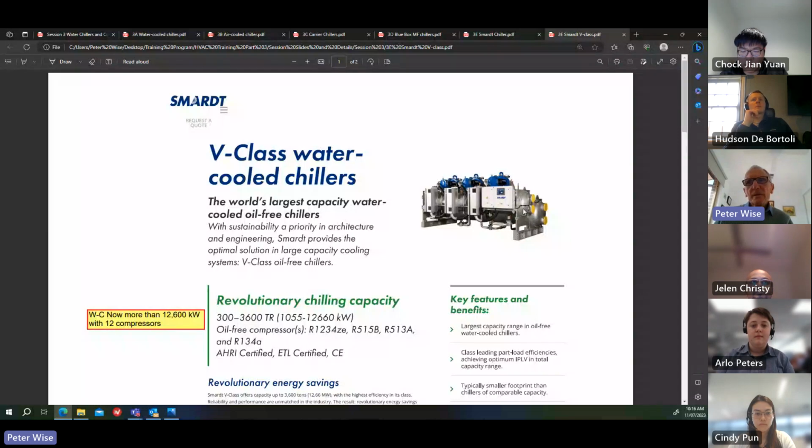And the end tube sheet there, they call that the tube sheet, that plate that these boxes are fitted to, that's stainless steel as well. So that's an option that's available with these machines. It does cost more money, but there's always the corrosion issue with condenser water systems that we've talked about before. So that's something to consider as well, to spend a bit more money and reduce your corrosion risk.